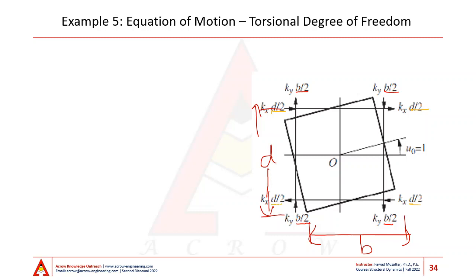Now these columns, the horizontal deformation also adds up to be equal to 0, which means that if my columns are of the same dimensions and if all of the columns are prismatic, then the rotation through O will not cause the slab to translate in any of those directions.